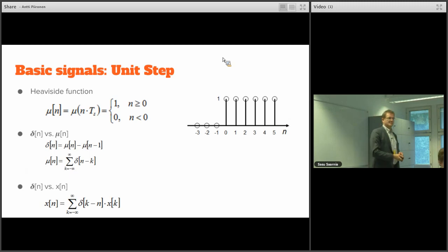A square wave is more or less the same as having a periodic series of Heaviside functions with some time delay. So you turn the signal on with the Heaviside or unit step function, and you can also turn it off by subtracting a Heaviside function. That's how you generate pulses that you can use to test your system.